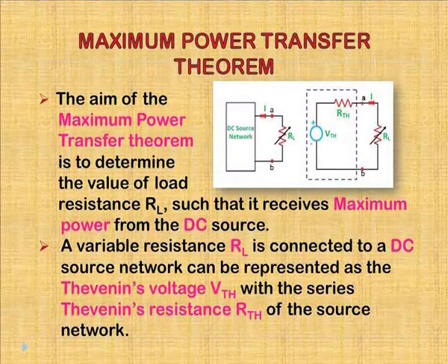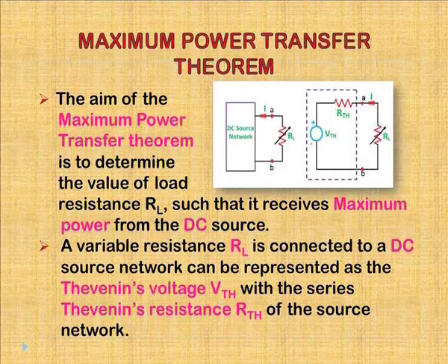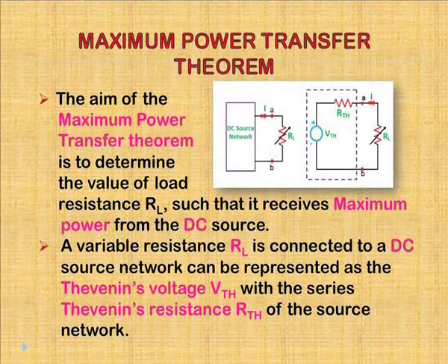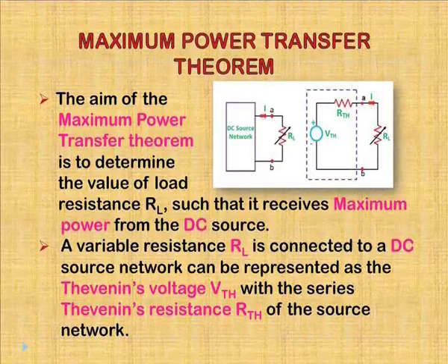If we are given any circuit, we know we can make its voltage equivalent circuit. Now, if we want to connect a load for which we want to get the maximum power, then what should be its value? As we know, if RL is 0, then we get the maximum current, and if the RL is infinite, that is the RL has its maximum value, then we get the maximum voltage but no current. In both the extreme cases, we get the load power as 0.